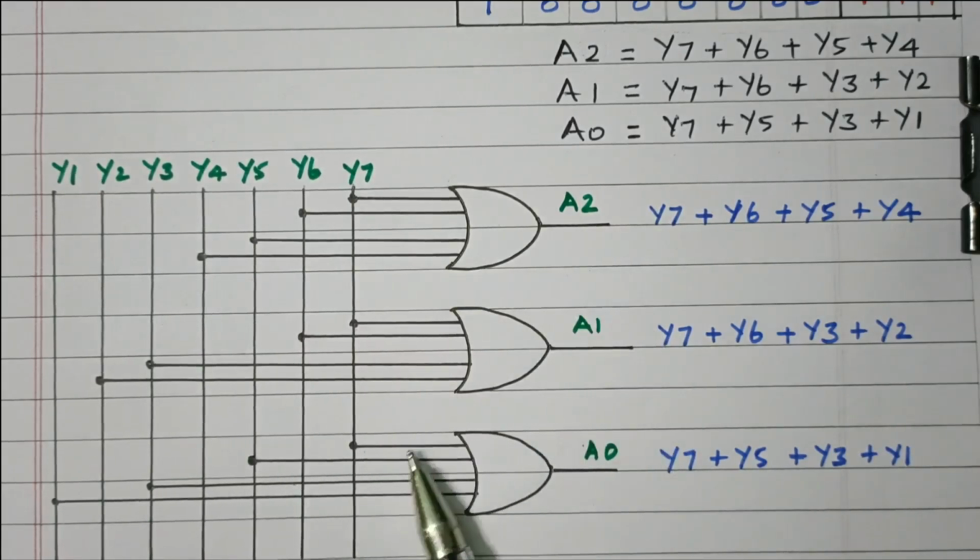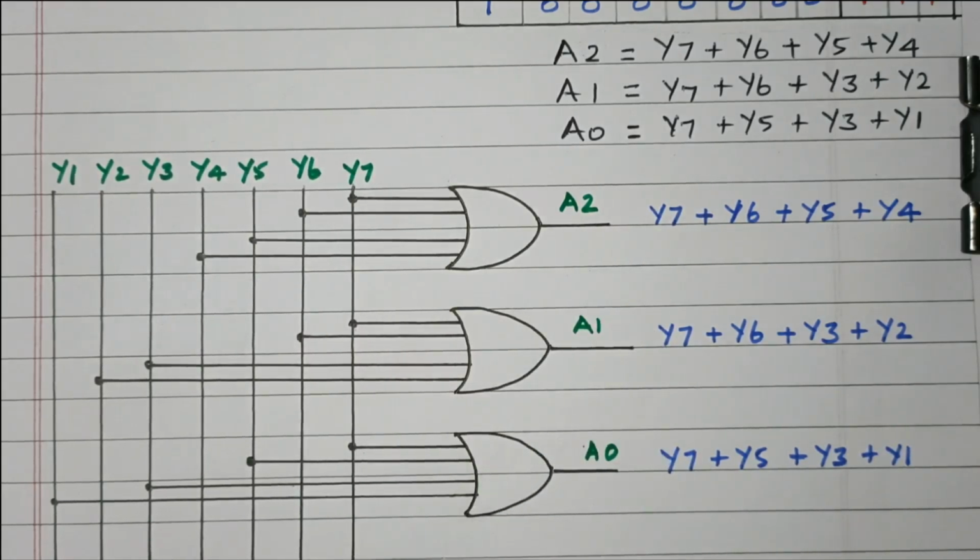Similarly here also, right? So in this video, we discussed the 8 to 3 encoder, also called octal to binary encoder, because of 8 inputs and 3 outputs. We discussed the block diagram, truth table, logical expression, then the logical expression implemented with logic gates.